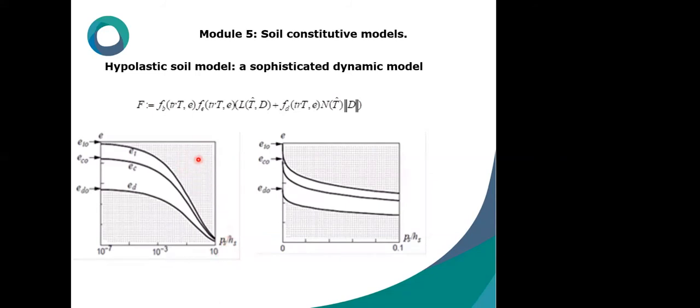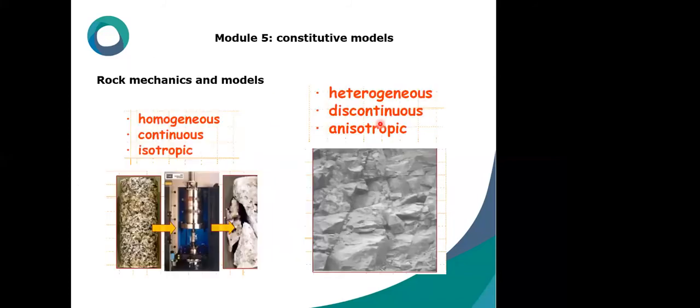And this gray part shows the impossible state for the soil grains, and this model can properly simulate soil dynamic behavior and hysteresis loops, and can generate them during seismic excitation. It also can show soil-structure interaction very well. You can see the tensorial equation of this model here, as I said before.